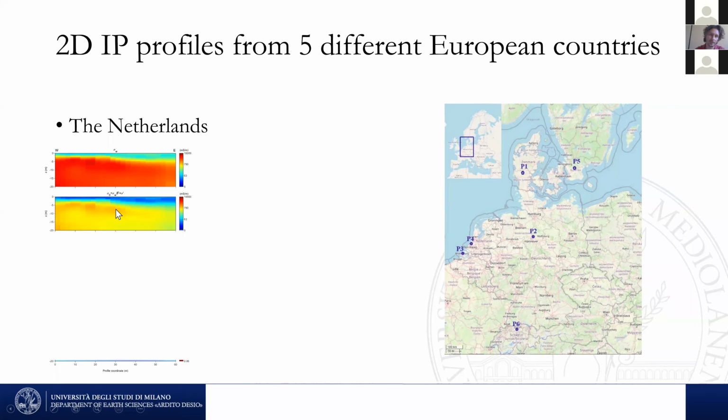So this is the total conductivity compared to the water conductivity itself. But what is most interesting in this slide is the estimation of the permeability. Here, our imaging of the hydraulic conductivity actually tells us that there is a clay layer with low permeability in the left part of our model.